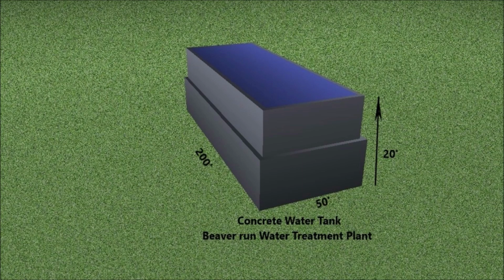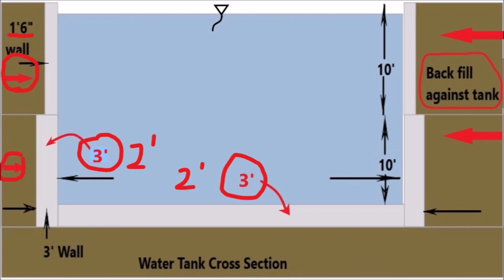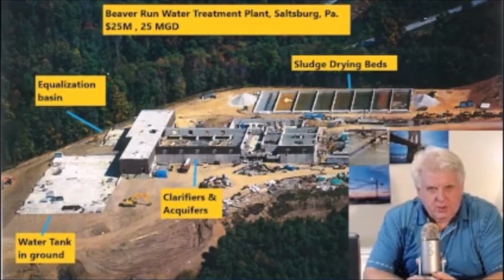The structural value engineer suggested that the base and the walls could be reduced in size, and he provided structural calculations and schematic drawings confirming that the compacted backfilled earth that surrounds the tank would help support the tank and the water within it. His calculations and redesign showed a 2-foot concrete base in lieu of the 3-foot original design and 2-foot sides in lieu of the 3-foot sides. We estimated about a savings around $200,000 for the project.